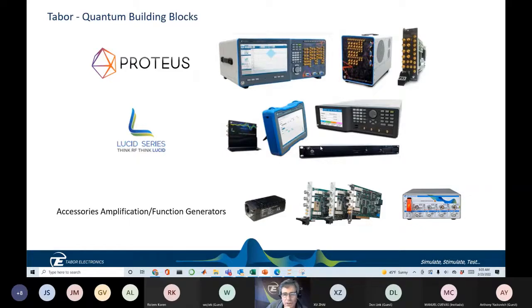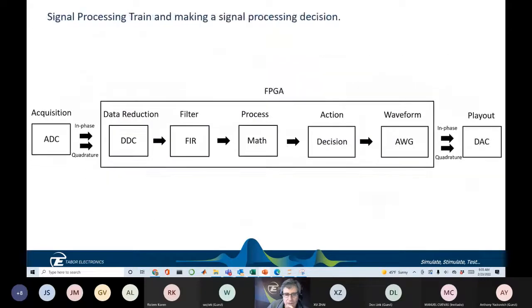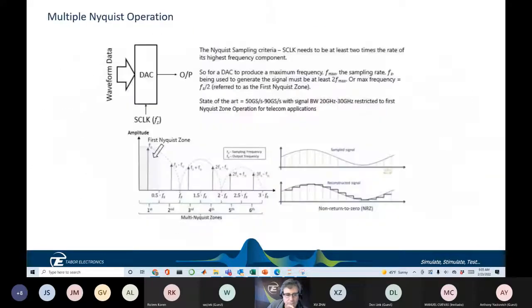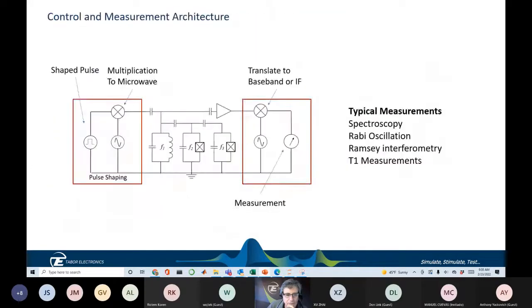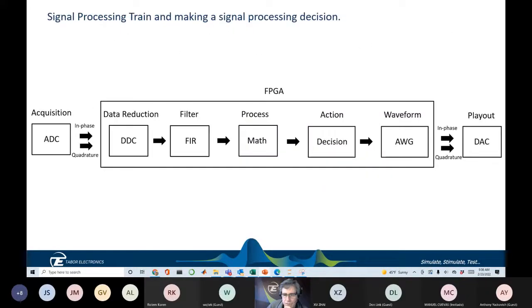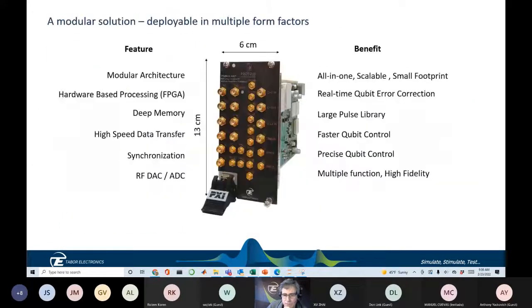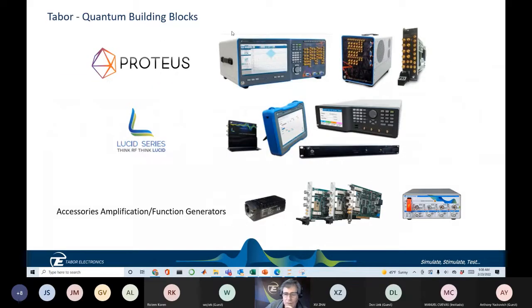And so if you want to use it in the traditional method, I'm just going back loads of slides now, with the signal generator, lower frequency ARB, we supply that as well, because the Proteus comes in 1.25, 2.5, and 9 gigasample options. So at various price points. So you can either use it direct to RF or with a local oscillator and up converter.